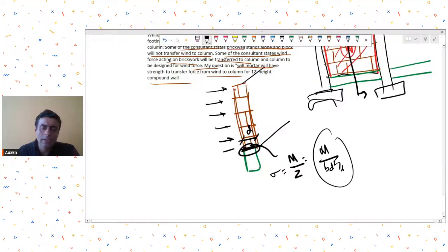So now you need to check the tensile stresses that will be developed, whether your mortar is sufficient to take these tensile stresses, and also whether your width is sufficient or not. These calculations and the permissible mortar stresses are given in this Indian standard. I am forgetting the name of this Indian standard, but for load bearing masonry, you have this Indian standard, and it does the checking for lateral loads also. So you can refer to those calculations for better understanding.